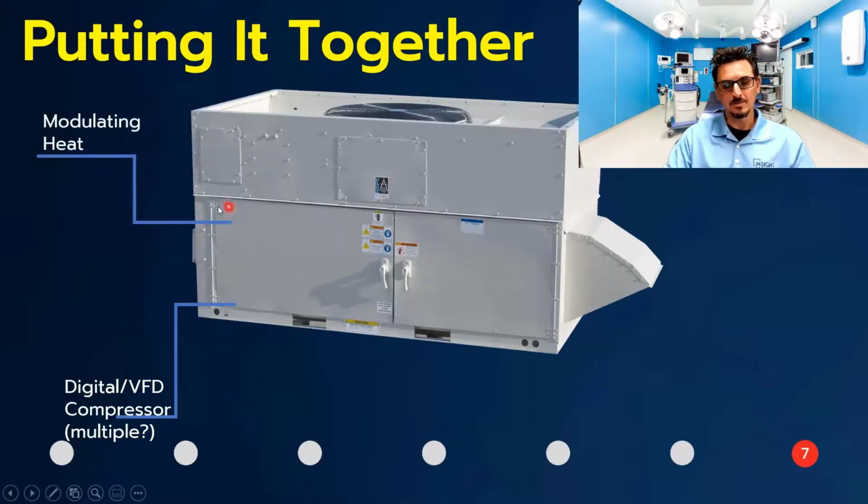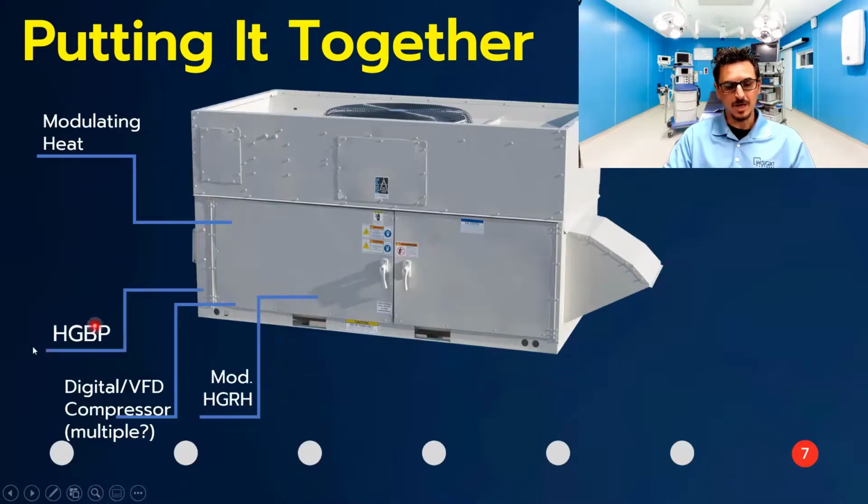Modulating heating. So your primary heat source should always be modulating. Modulating hot gas reheat downstream of your cooling coil. It's a must for dehumidification. I sometimes will include hot gas bypass in addition to all this stuff, because at extreme low load conditions, it might prevent your compressor from tripping off. Different reps have different opinions on that and different experiences. I've done it like this before and it seems to work real well as an extreme part load freeze protection, but it may or may not be needed. It really has to be looked at on an individual basis.